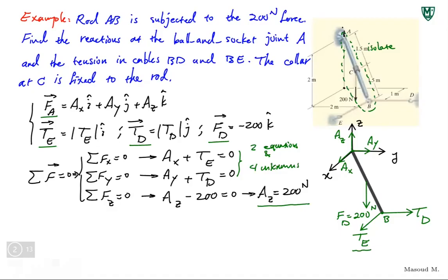Aside from all the forces should be 0, we also know that summation or vector sum of all the moments should be 0 too. So I'll do summation of moment. Which point I have to take the moment about? Well, I don't have to. Which point is the easiest point? About point A. Exactly. Thank you, Sama. A is a vector. Why A? Because we have most number of unknown forces applied at point A.